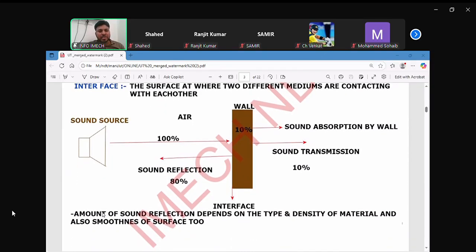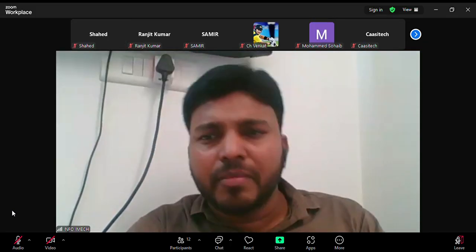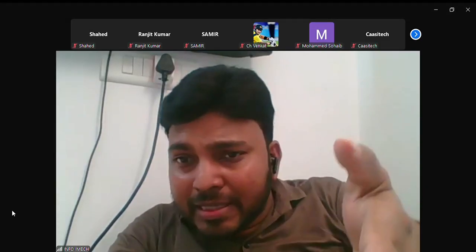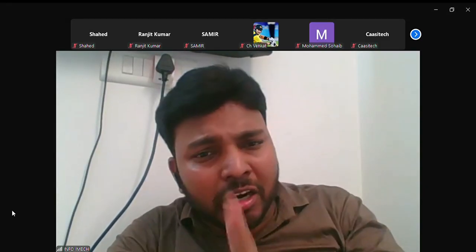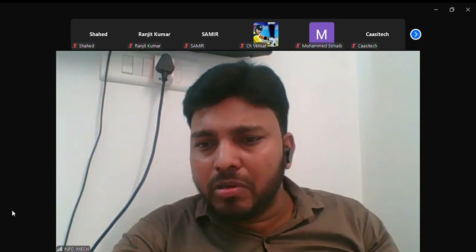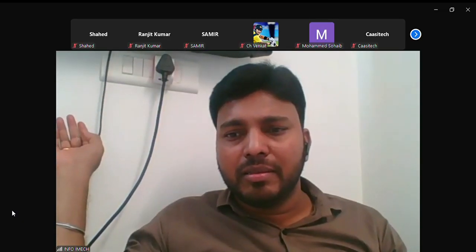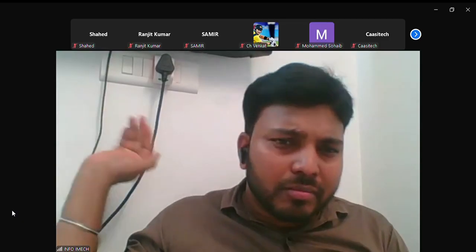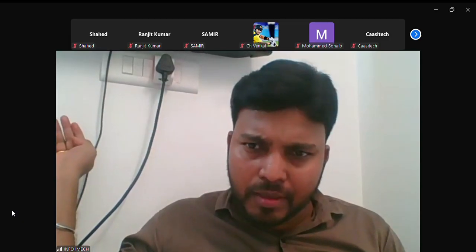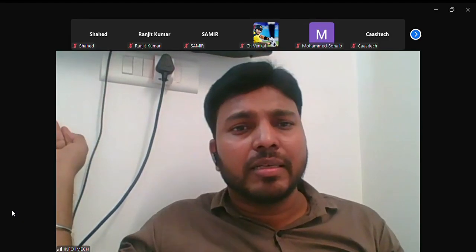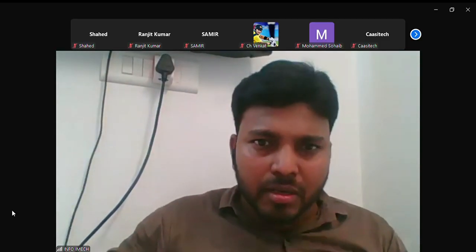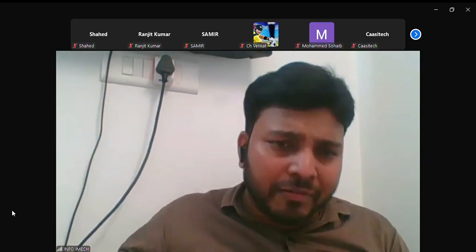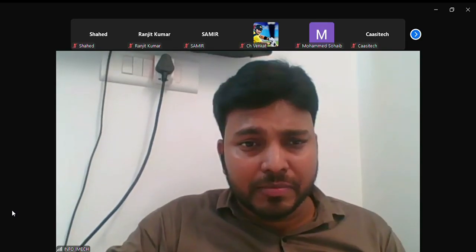The amount of sound reflection depends on the type and density of the material. See here, guys, I have mentioned 80%, but it is not fixed. If the wall is completely polished, like a super plastered wall, reflection will increase. When the wall is completely rough, reflection decreases.